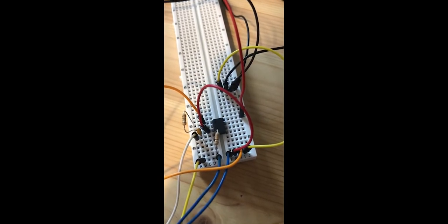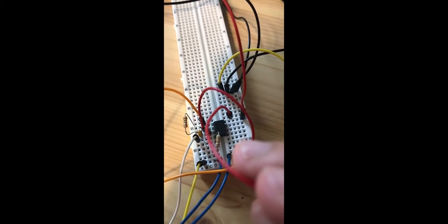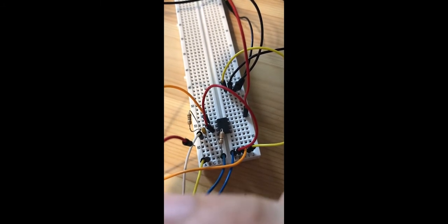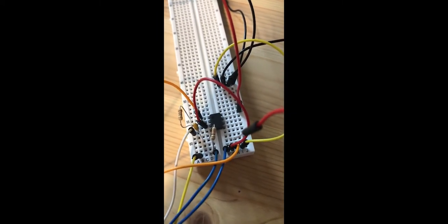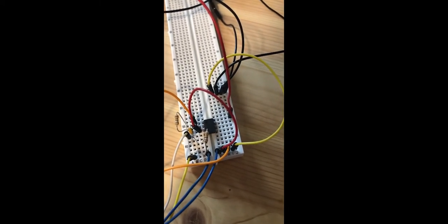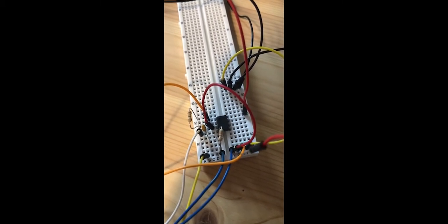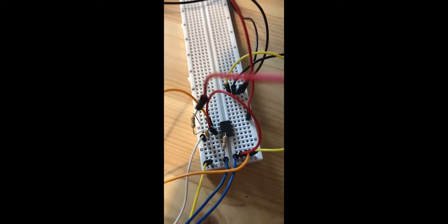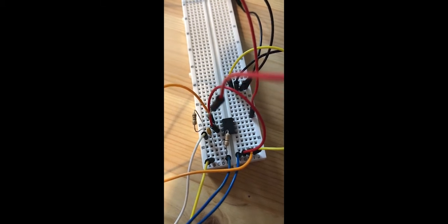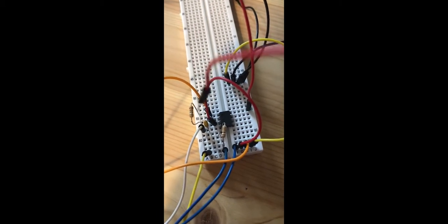Here you can see the circuit. Again, we have the supply connections, pin 8 and pin 4, the white wire and red wire here. And then other connections like ground are like before, and this is the wire that is providing 2 grounds like before. And this wire and this wire, the orange here and blue here are the grounds of the oscilloscope. You again need to, as I mentioned before, wire the pin 3 of the op-amp.